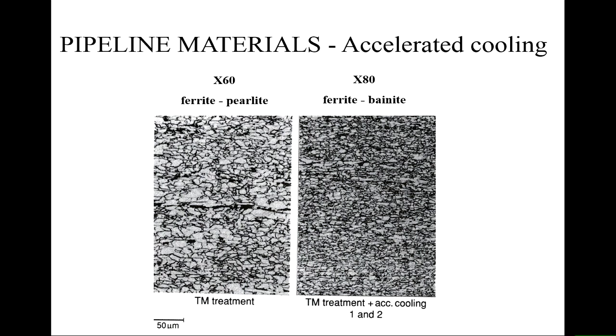We've got ferrite grains, we've got dark regions, but if you go in with a high power microscope, you'll find this is bainite. Instead of having plates, lamellar sheets of iron carbide, it has little precipitates, little dots of iron carbide. But you need a pretty powerful microscope to actually be able to see that. This is a 50 micron scale, so the grain size in here is going to be of the order of 10, 20 microns. The grain size here is 10 microns or less.